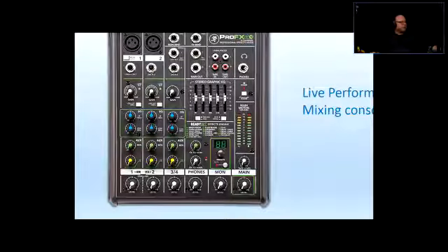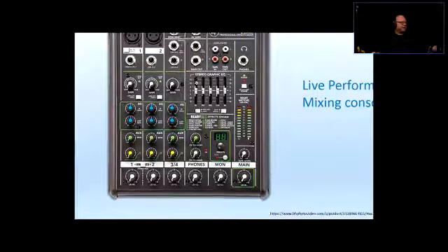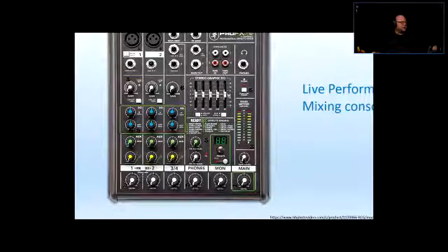You also have a headphone output if you want, and sometimes people ask what the tape is. Well, we're going to go over that a little bit. There's a little bit of an EQ here, and that refers to the main outputs. So you can still EQ, or equalize, the lows, mids, and highs. The general rule is to try not to amplify the frequencies. Try to have a good mix, and then if you need something, try to subtract frequencies. That's the best way of using mixing boards, right?